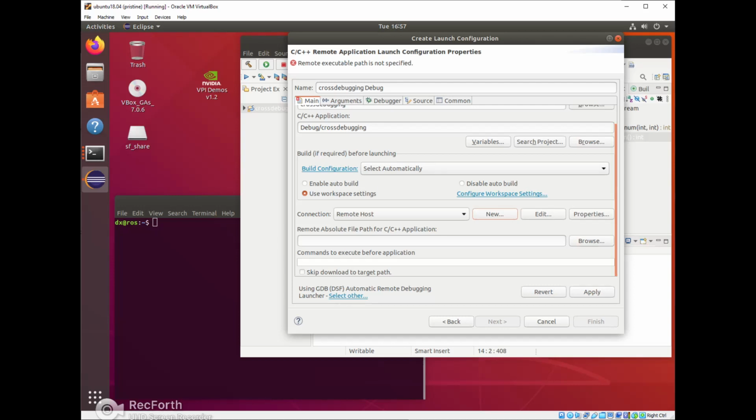And then you're gonna have to tell where to copy this cross-compiled binary. You're gonna tell the IDE where to put it in the remote ARM64 board. So, let's just say, put it into the TMP folder. But first, we'll notice that there's a browse button here.